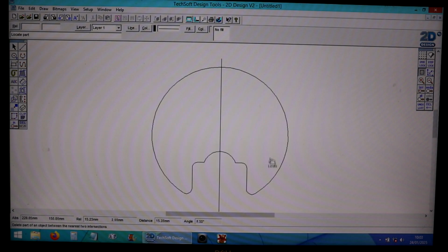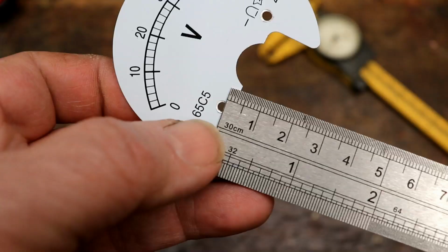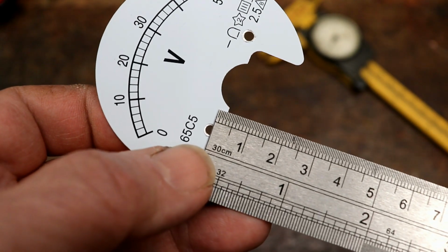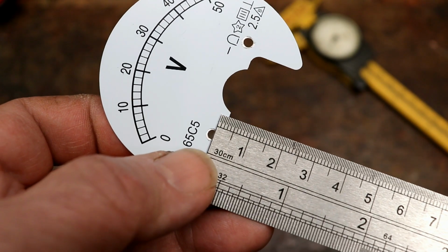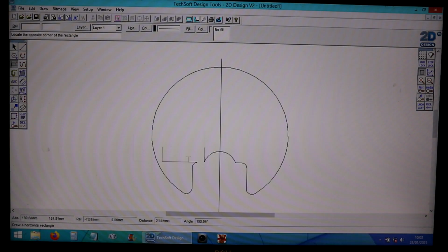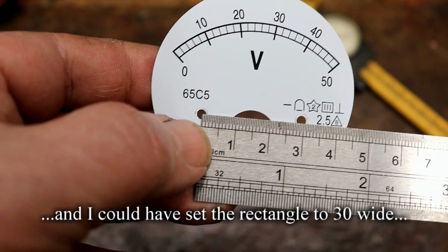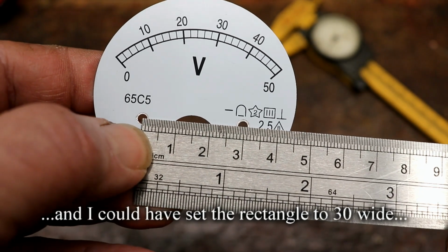So the next part of this, the final part of the structure, you'll be pleased to hear, are the 2 screw holes, which obviously are very important. So we're going to measure the height they are from this point, and it's 2.5. So let's get another one of these, and we're going to make it, I don't know, 30 by 2.5. There we are. So that's going to give us the top line, the height of each of those 2 holes, and they are 30 millimeters apart.